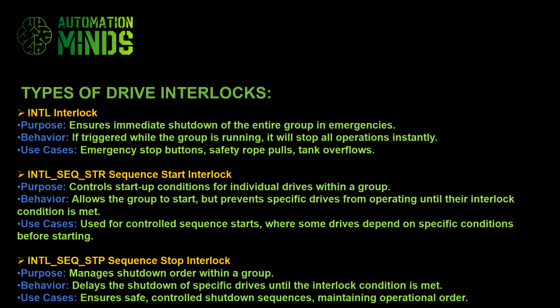for the drives. It's also worth noting that sequence start and stop interlocks are usually not active when the drive is in local mode. This makes sense because during maintenance or inspections, there may be a need to test a single drive in isolation. In such cases, forcing the activation of other drives would defeat the purpose.